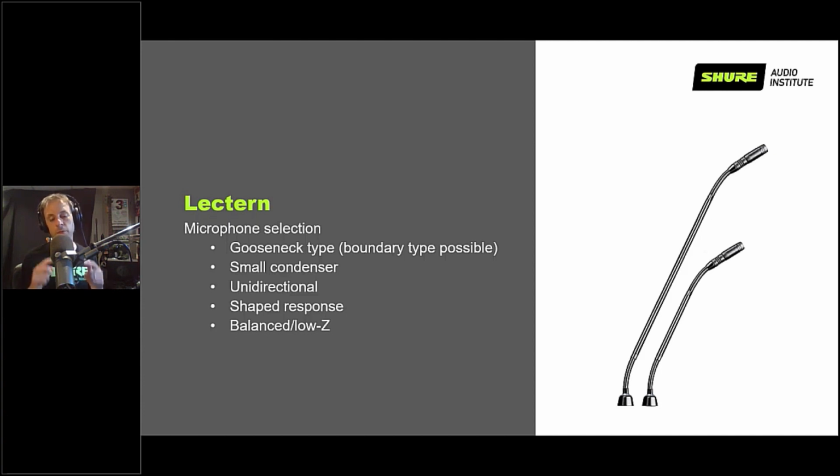Remember, the only difference between a cardioid and an omnidirectional microphone is that the omnidirectional mic picks up 360 degrees around the microphone. But if you wander off to the side like that, it doesn't really help you. You're still getting quieter because you're moving too far away from the microphone. So unless your pastor wanders to the other side of the lectern and speaks into the back of the microphone, going to an omnidirectional mic doesn't really help there.